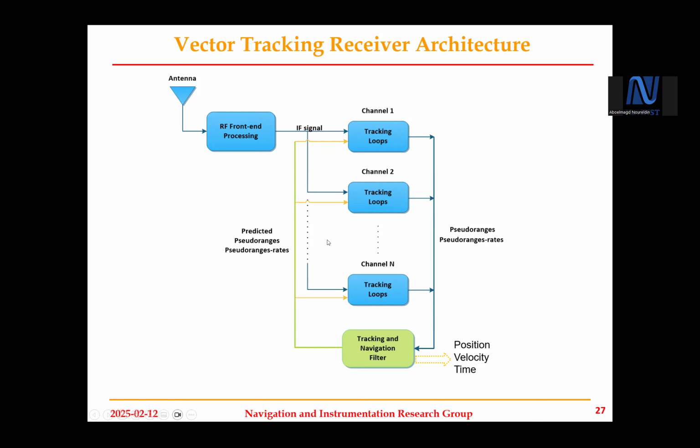By the way, for another reason, vector tracking based receivers are called sensitive receivers, but just by coincidence I use the term sensitive here. So this implementation could be fragile sometimes. If you feed the wrong information, you may destroy the whole tracking loops at once.